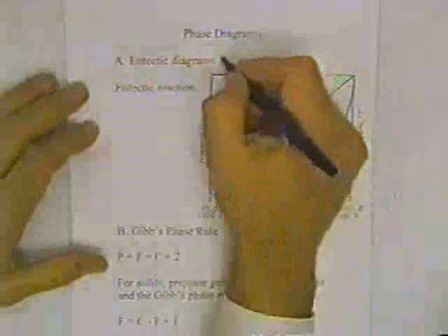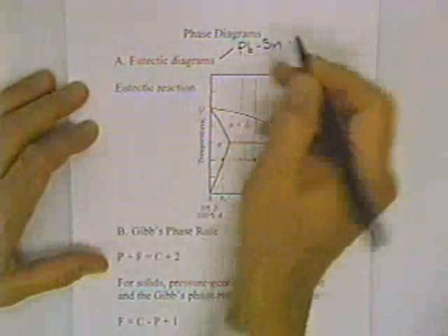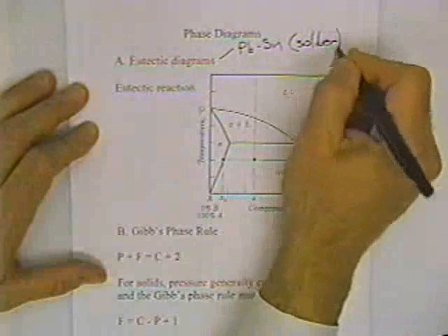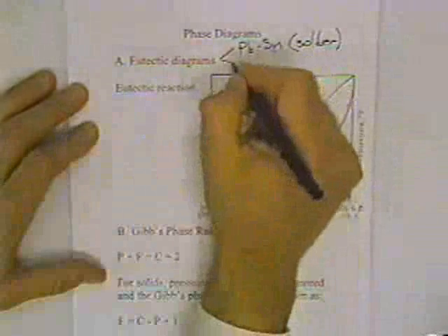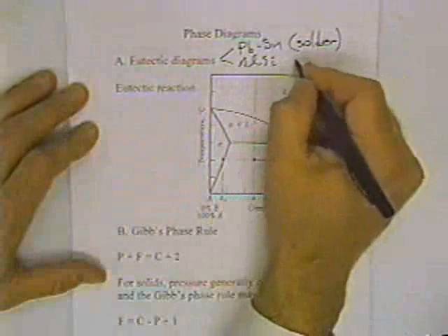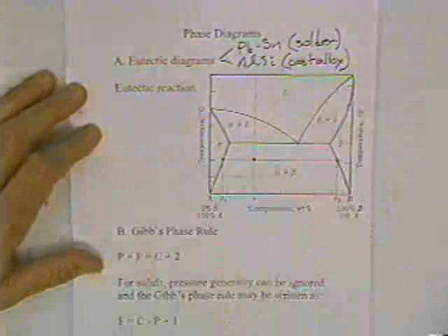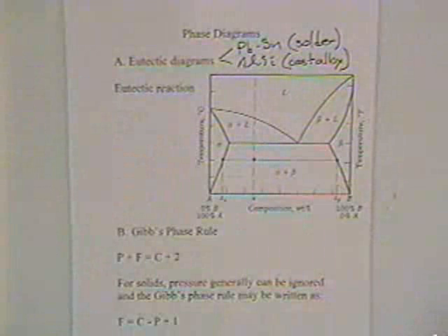The phase diagram that's shown on page 21 represents a eutectic system. There's a number of industrially important eutectic systems. The lead-tin system, which would be the basis for solder, would be one important one, and aluminum silicon, which is used as a cast alloy in a variety of different parts. Hand grips for bicycles, sometimes lightweight parts of the suspension system.